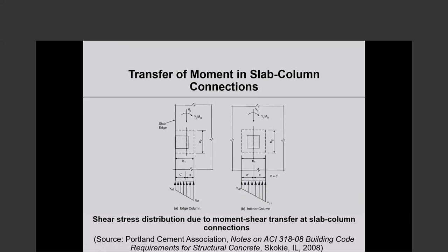On this face, the stresses due to the moment transfer and the direct shear will be additive. So this is what I was trying to say. I think the pictures are more graphic.